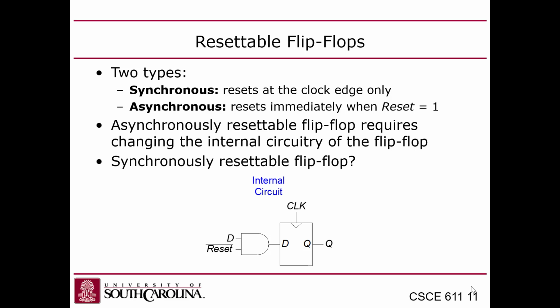Resets can also be synchronous or asynchronous. Synchronous resets only on the clock edge. So a synchronously reset flip-flop will reset, but you have to have the reset input asserted, and you have to have a clock edge. Meaning that there's a delay. You tell it to reset, but it doesn't reset right away. It resets on the next rising clock edge. An asynchronous reset will reset it immediately. The FPGAs support asynchronous resets natively. So I've never seen a compelling reason not to use an asynchronous reset.